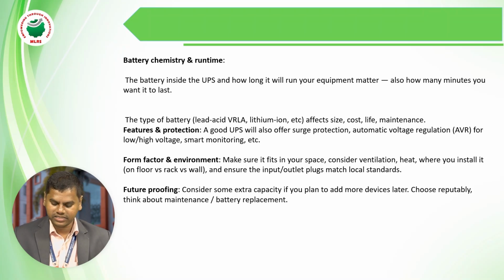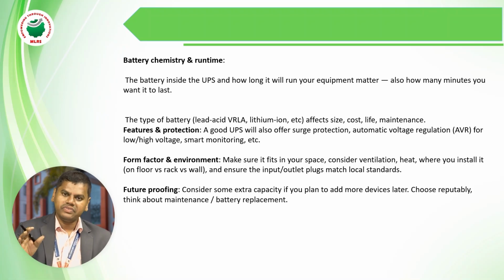The type affects size, cost, life and maintenance. Next, features and protection: a good UPS will also offer surge protection, automatic voltage regulation, AVR, for low or high voltage, smart monitoring, etc. That is the features and protection.